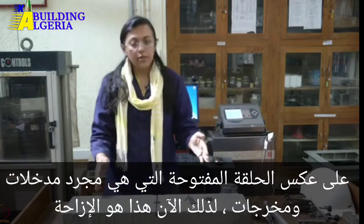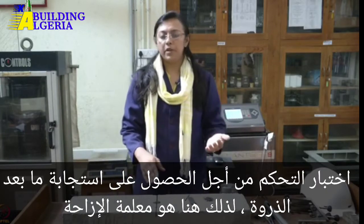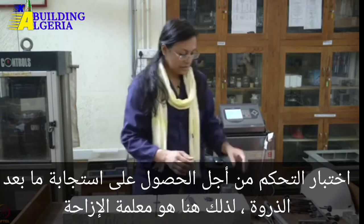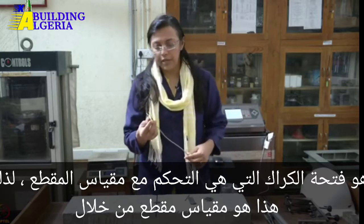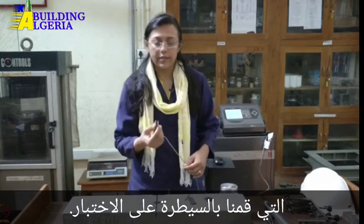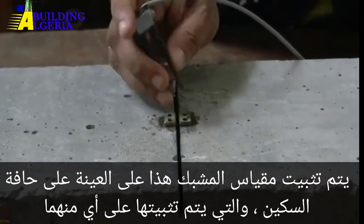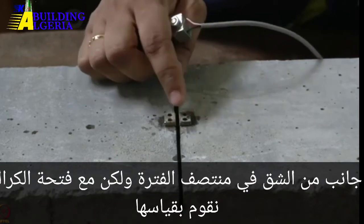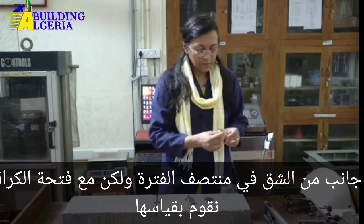So now this is a displacement control test in order to get the post peak response. Here the displacement parameter is crack opening, which is controlled with the clip gauge. This is the clip gauge through which we control the test. This clip gauge is fixed onto the specimen on a knife edge, which is fixed on either side of the notch at the midspan. But along with crack opening, we are even measuring deflection.